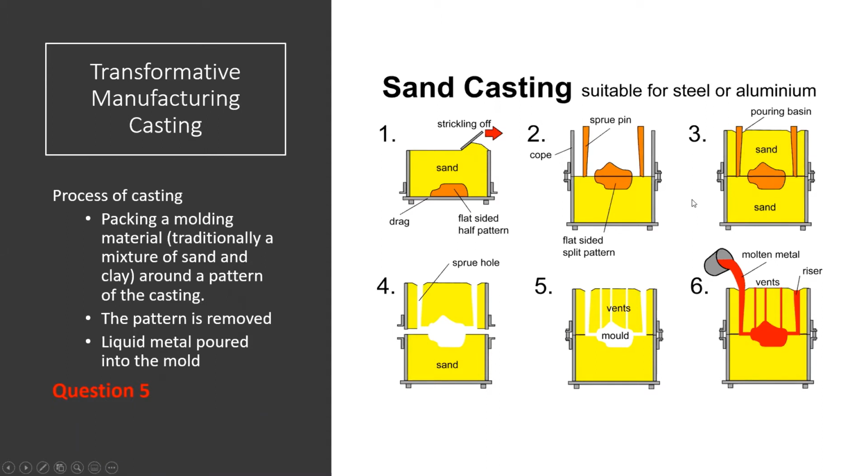So once all your sand is packed in there, then you remove all of that stuff. So you remove the mold shape. Now you're left with this negative void. So you put everything back together, you put the boxes back together, and now you have this space where you can actually pour your metal. So you pour your metal in, and you've got your shape. It'll fill up the void where the sand is not.